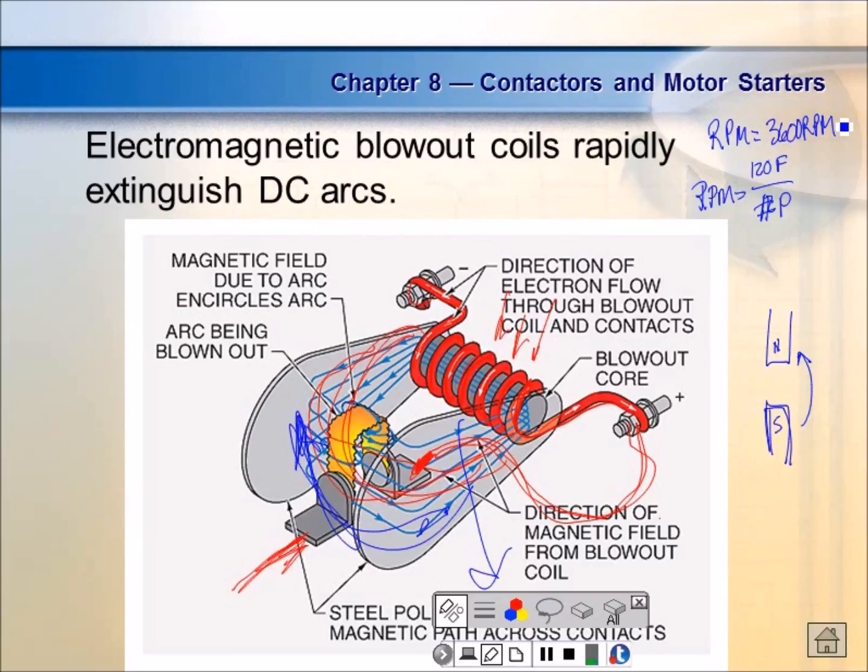Everybody follow this? Of course, with electronics, what we have now is what we call variable frequency drives. There's more to it, and we'll try to explain it a little bit when we look at that. We've got one back there we can see. But what I can do with that is change the frequency. Y'all understand? That makes sense. So a variable frequency drive and the motor is going to be cheaper than a DC drive and a DC motor. So now AC motors are starting to dominate variable frequency drive speed control.